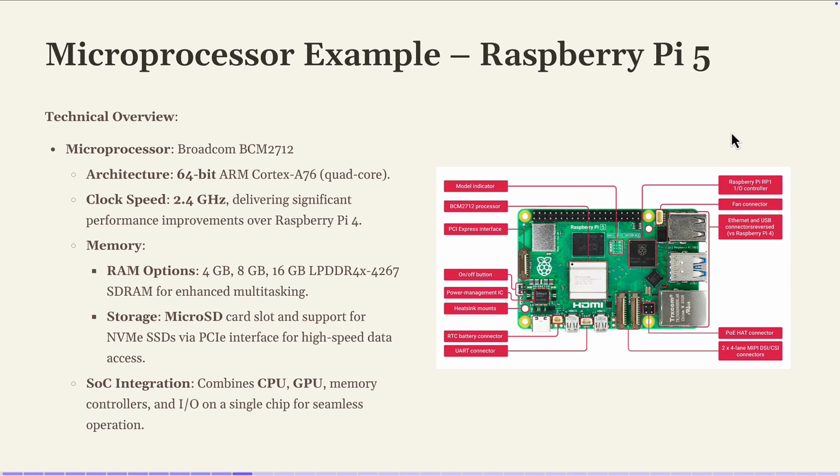Basically there are different levels, because there is a quantization from 0 to 1023. And this level will give some particular values, for example, for the temperature. For the temperature, you can have a range of temperature. How can you differentiate between them? It will be encoded into values between 0 and 1023.